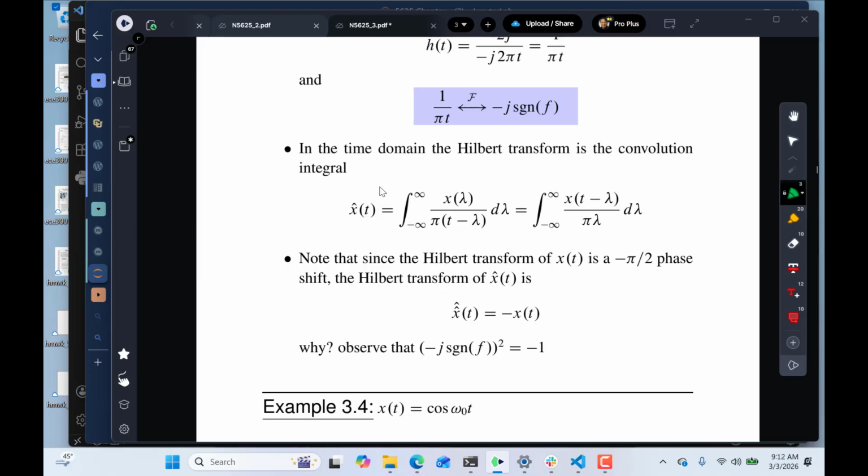It's better, though, to just think of it, like I said, as the phase shift. So this example right here just says if you phase shift by pi over 2, that says that if you do 2 Hilbert transforms, cascading 2 filters in a row, you'll shift by 180. And what does 180 do to any signal? It's inverting it, right? So this property right here follows, and you're not seeing double with your vision. It's really on the page. I have 2 hats on the page.